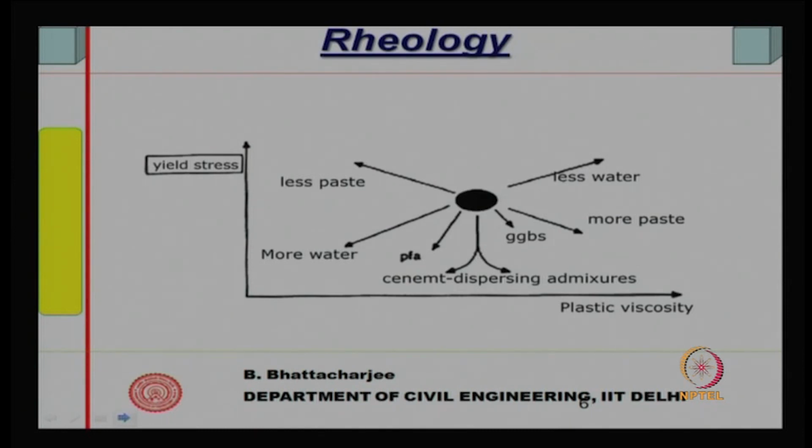concrete properties. You see, the fresh concrete or fresh paste can be considered to be a plastic material. So, a plastic material is one that is in a plastic state, and plastic state is one where under a constant load it will deform continuously. A solid deforms under load and stress is proportional to strain, in whatever form it is, shear stress is proportional to shear strain.